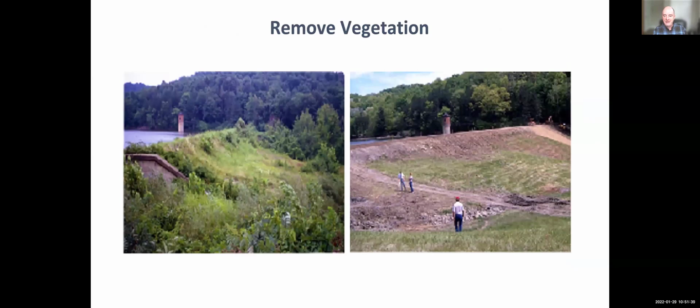Not the greatest photographs, but it's a before and after. So you can see how the vegetation, the shrubs primarily, but some trees at the very far end, were getting out of control, and they've cleaned the whole thing up. And when your dam looks like a dam, you're doing a good job. If you can see the whole thing and do your quick inspections, you've done a good job.